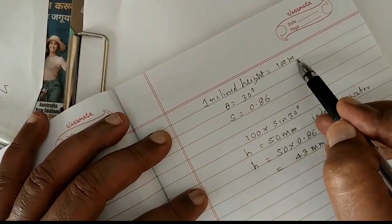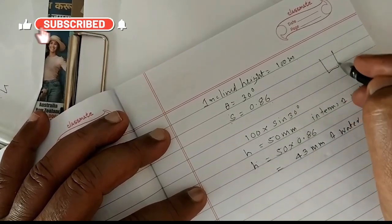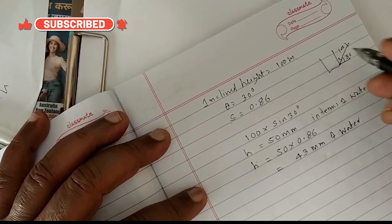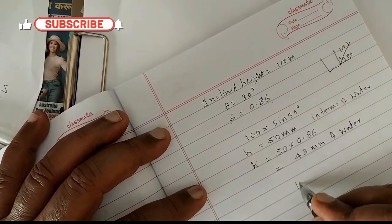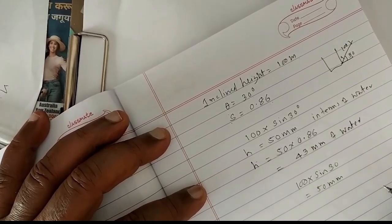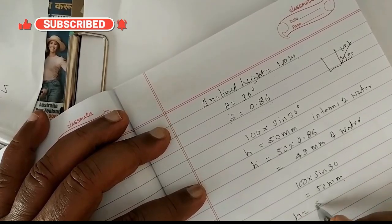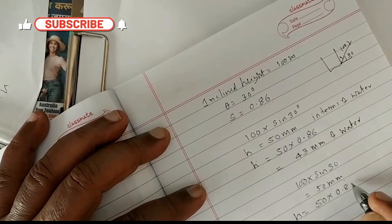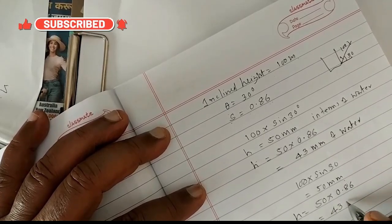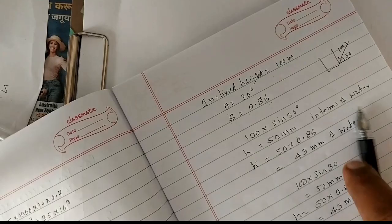So I'll repeat the problem here. The inclined height is 100 millimeter, angle is 30 degree, specific gravity is 0.86. So 100 into sine 30, that is 50 millimeter. And the reservoir contains oil whose specific gravity is 0.86. So H is equal to 50 into 0.86, that is 43 millimeter of water. So B is the correct option in this problem.